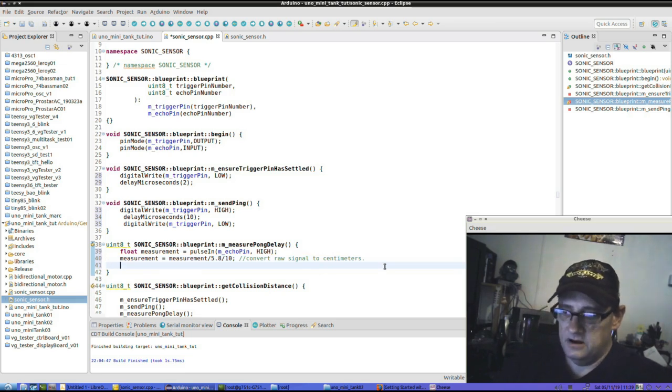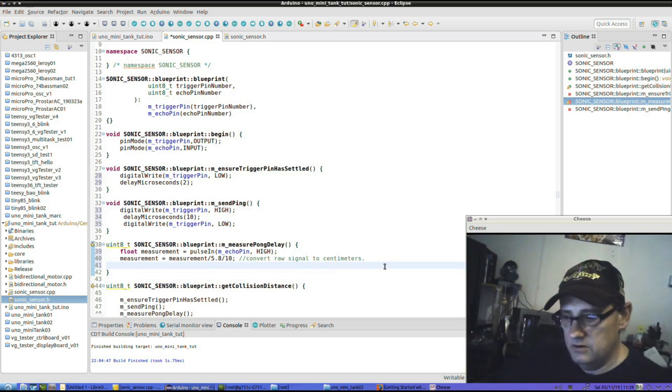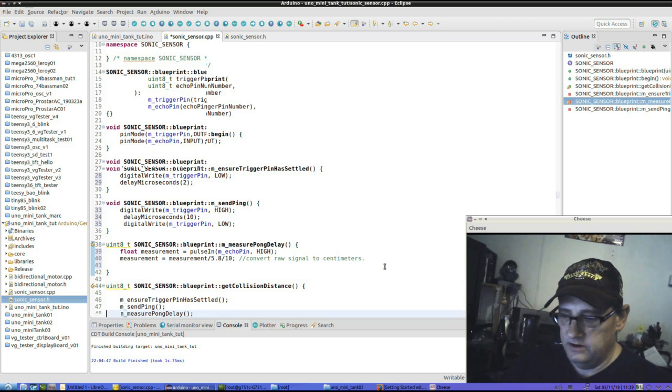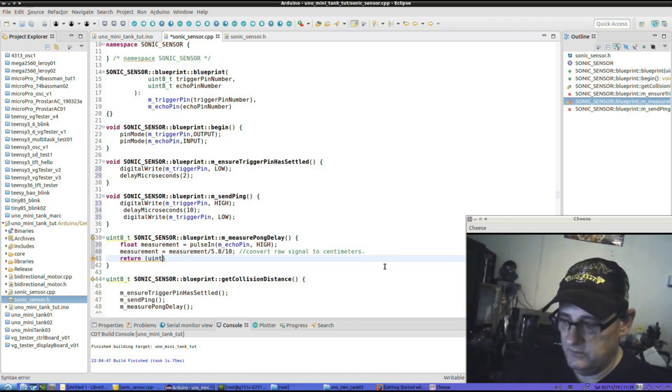And then the next thing we want to do is say, hey, what are we giving back here? What am I going to return to whoever has called me, which would be down here. So we say return what information? Return, and of course we can say, hey, convert this to a uint8_t data type measurement, because it's going to be scaled way down. It'll fit in an 8-bit data type.